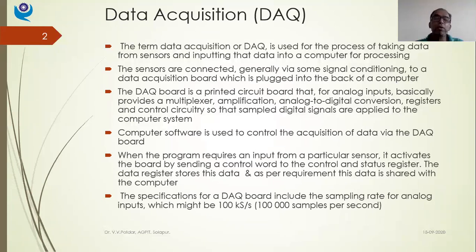The computer software is used to control the acquisition of data via the DAQ board. When the program requires an input from a particular sensor, it activates the board by sending a control word. See, listen to me very carefully. When the program requires an input from a particular sensor, it activates the board by sending a control word to the control and status register.